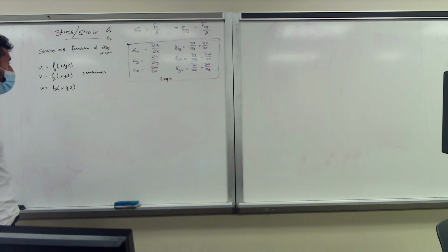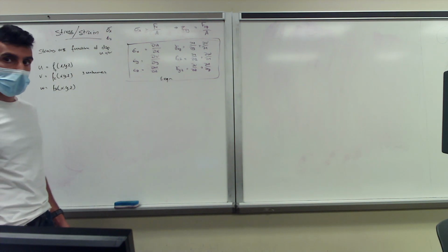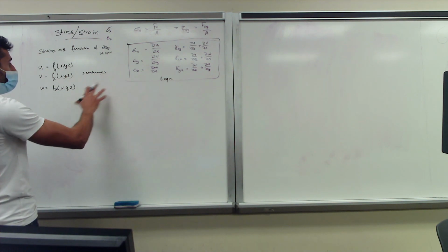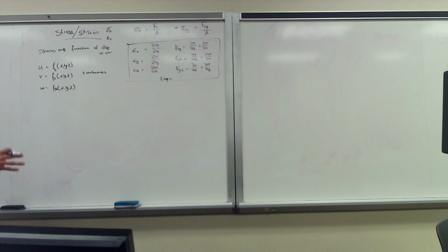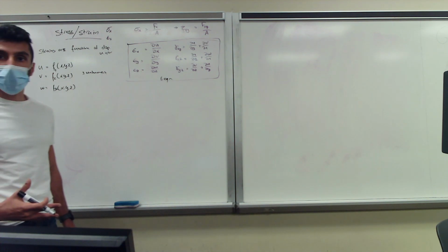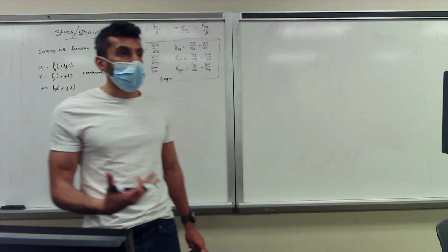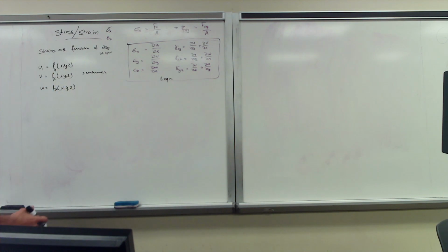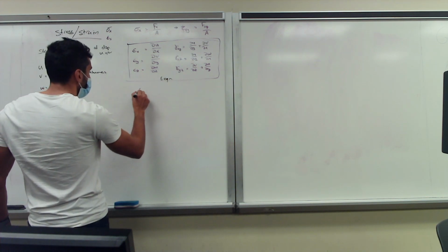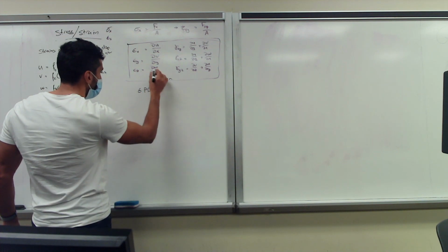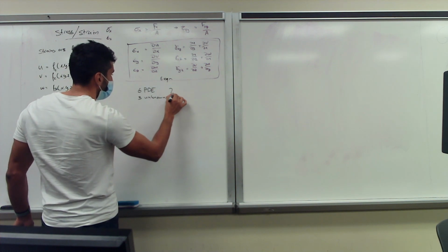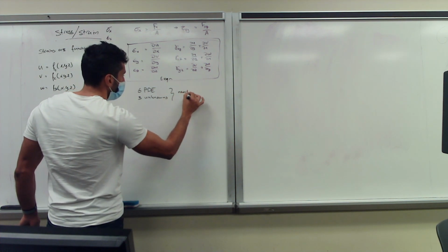And the problem is that we can come up with solutions that are basically trivial solutions. So in order to have a solution that works, that maps the correct strain field with the correct displacement field, we need to come up with certain compatibility equations that you can test your function against to see if that's actually the correct solution to our problem. So the fact that we have 6 partial differential equations and 3 unknowns results in the need for some compatibility equations.